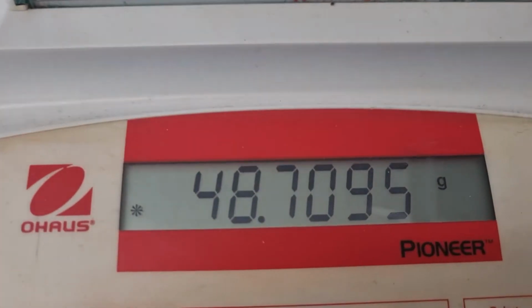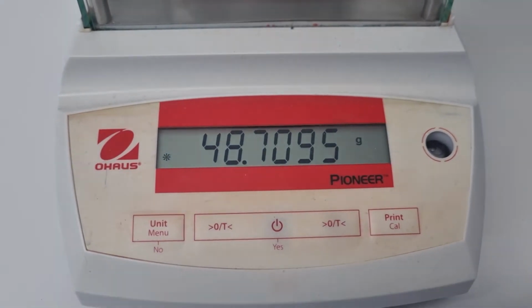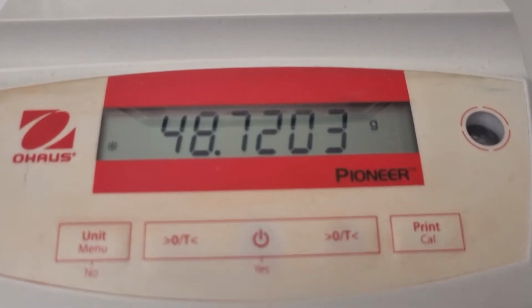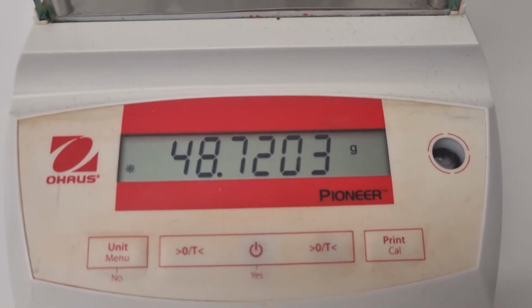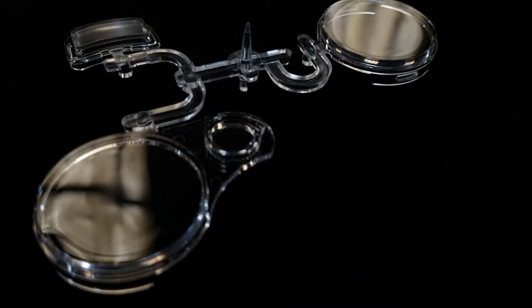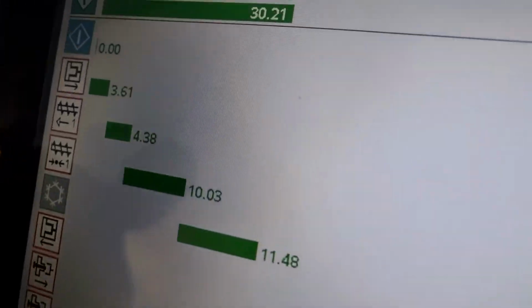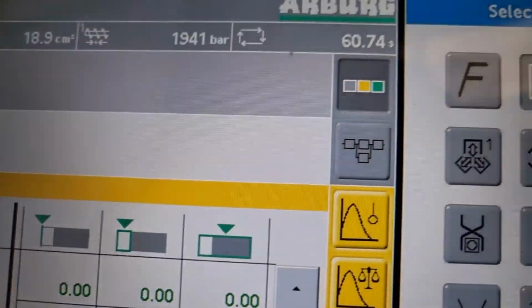The downside to cold runner systems is that they are less reliable and accurate compared to hot runner systems. There can be more variation between shots, which can lead to higher scrap rates when producing parts with tight tolerances or high-spec surface finishes. Another factor to consider is the cycle time required to produce the same part with a cold and hot runner system.